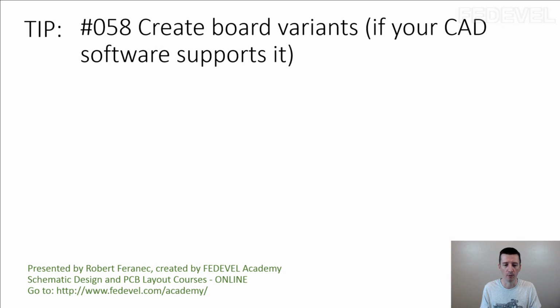Sometimes it can be much more difficult. Sometimes you need to describe some resistors, some capacitors, some connectors which are not fitted between the variants or which are fitted between the variants. So it can be very, very useful if your CAD software supports it, because it helps you minimize mistakes when you are creating documentation for manufacturing.